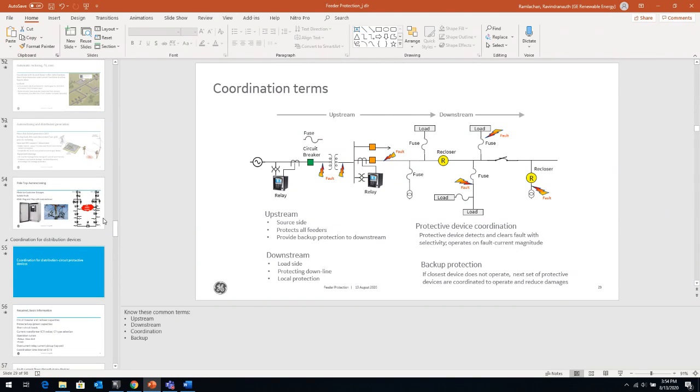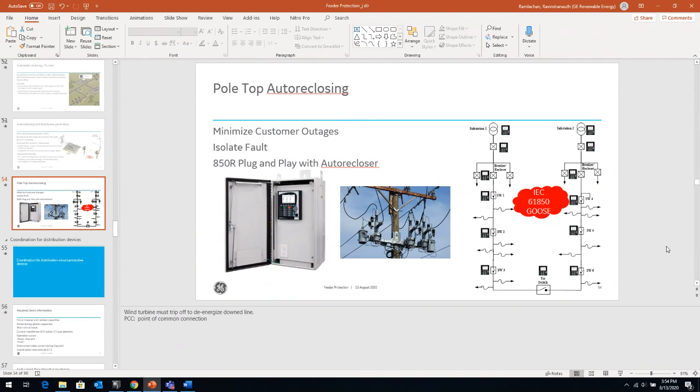One of them is the auto reclosing scheme. So instead of having, again, this coordination effect where I need to coordinate the auto recloser to the downstream ones, I can use the communications to do coordination, where I could send that blocking signal back either to the substation, and then the substation sends that signal to the relays on the pole. And I can do that with IEC 61850 GOOSE messaging.